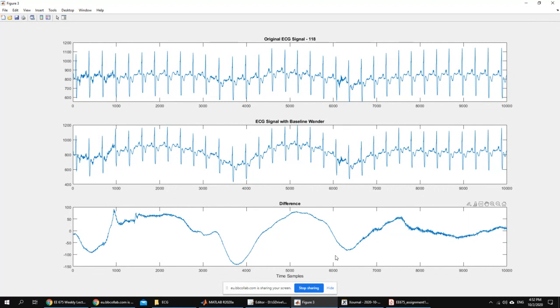Okay, so which frequency? What we said last time is that we should get an estimate of this artifact frequency. Maybe we can just consider it as a sinusoidal signal, so we can measure the difference between two peaks or two valleys here and get an estimate of how much frequency is there.